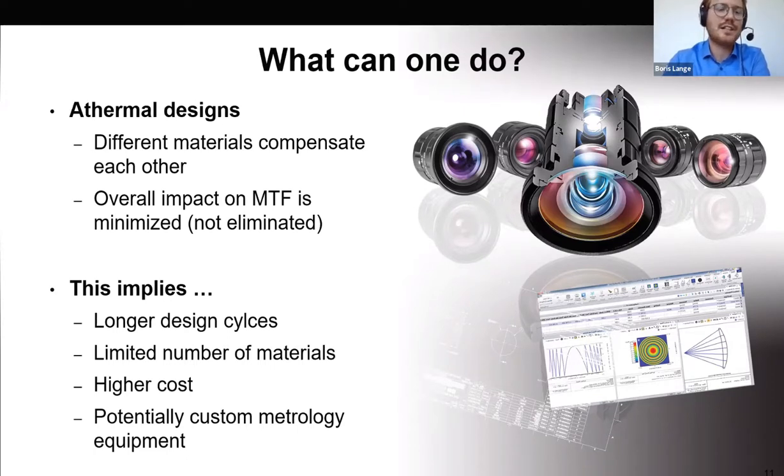I think a lot of that is actually coming from the recent trend over the last years that the automotive guys have such a big interest, autonomous driving and things like that. I think there was a big push on the metrology side where people said, all right, how did you guys in the optics industry measure that until now? And then our answer was, we take the lens, we measure MTF, we put it in a cabinet, we change temperature, we run some cycles, and then we measure MTF again afterwards. But measuring all of these parameters in situ, which is, again, eventually what matters to you in your applications, that has not been around for a long time, I think.